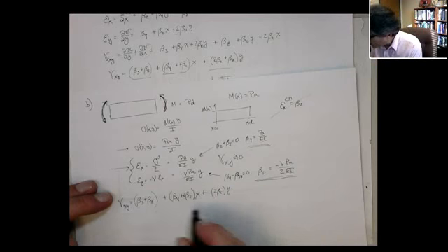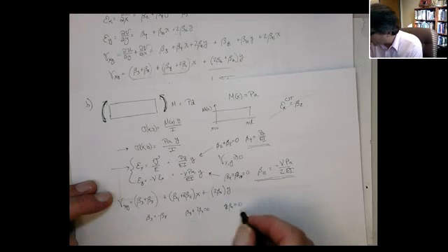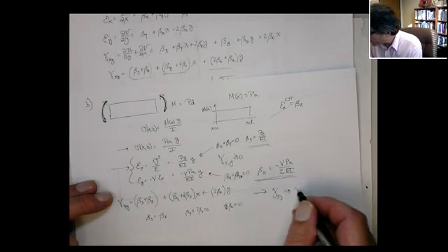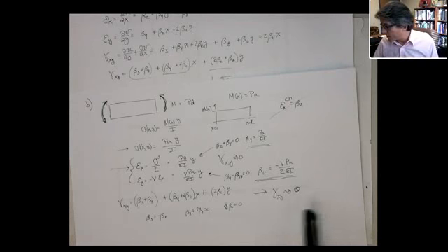Okay. So if beta 3 equals minus beta 8, and then beta 4 plus 2 beta 11 equals 0, and then 2 beta 6 equals 0, or beta 6 equals 0. This will basically get all the shear terms to roughly go to 0. It will nominally get small shear, so you can actually consider small shear also reproducible in this element. So you can actually get a low shear strain.